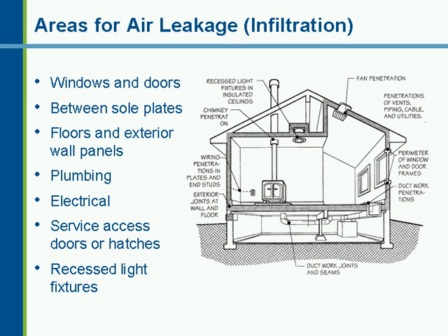And some more information on air leakage. The point I want to make is there is one place that is commonly missed when you are doing your air sealing, and that is behind the stairwells and exterior walls. The other one is your attic access hatches. If your attic access hatch is within the thermal building envelope, are you sealing it properly?